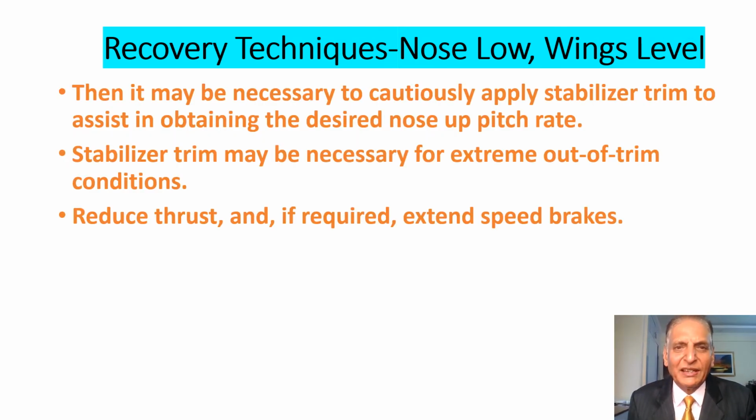Then it may be necessary to cautiously apply stabilizer trim to assist in obtaining the desired nose up pitch rate. Stabilizer trim may be necessary for extreme out of trim conditions. Then reduce thrust and, if required, extend speed brakes.